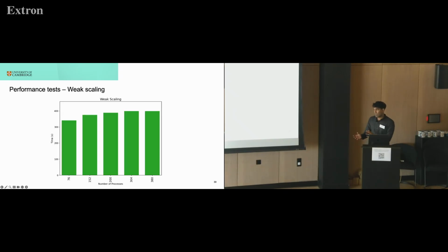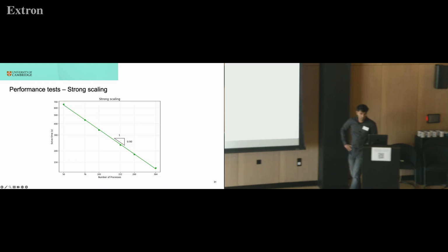Finally, as I said earlier, one of the key things we're looking at is exascale computations. So this result here is a weak scaling where I use around 100 DOFs per core. We're trying to see the processing power of each process. And we can see that generally this exhibits nice weak scaling results. And then for strong scaling, we did it on a 10 million DOF mesh, and we get pretty good parallel scalability using Hypre as a preconditioner.